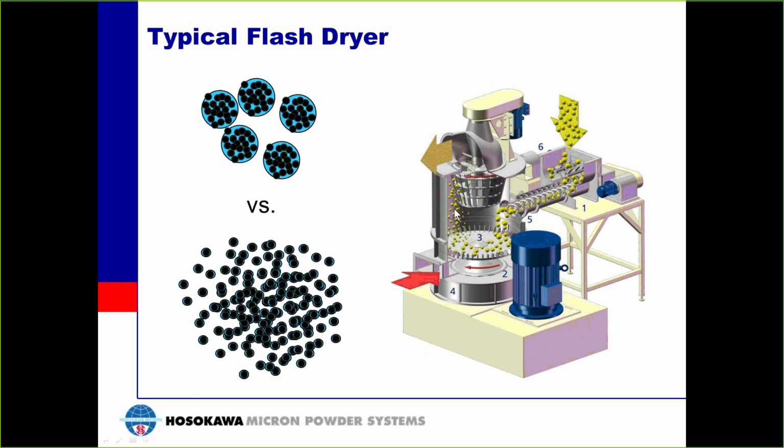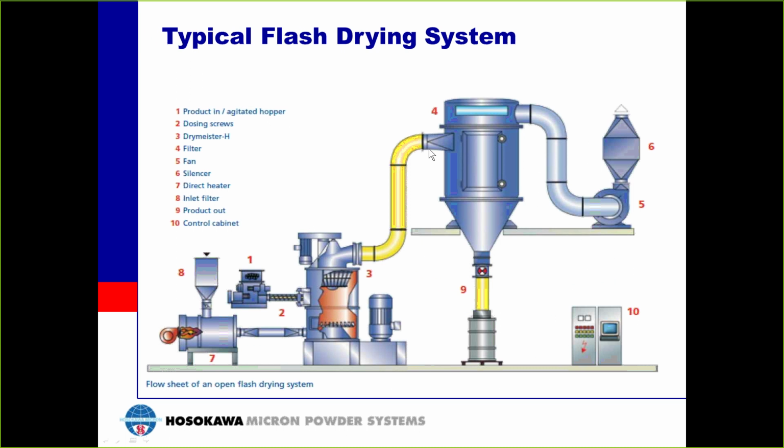Your fine dust is going to leave. For this machine shown is a dynamic air classifier. What this is going to do is any larger particles are going to get rejected. The theory behind this is any particles that are either held together by moisture or not dry, so if they look something like this, they would be rejected and they would be sent down to be redispersed. So going back a slide, you have dried your product, you're coming out through the classifier. You're going to be coming up, you're going to have a bag house which is going to collect your product. The water vapor is going to continue on to the blower, and then you're going to have a discharge silencer.